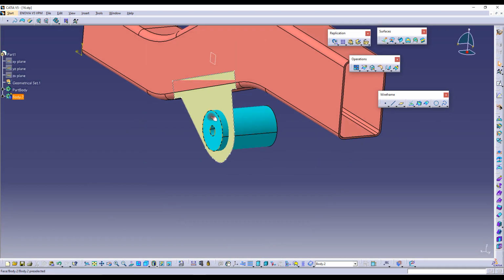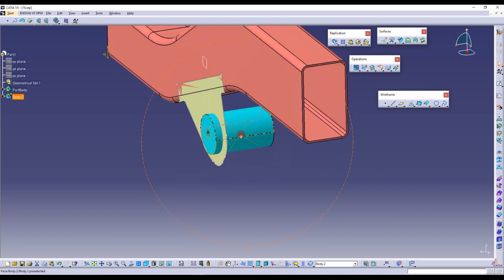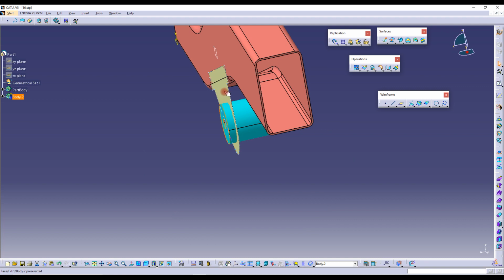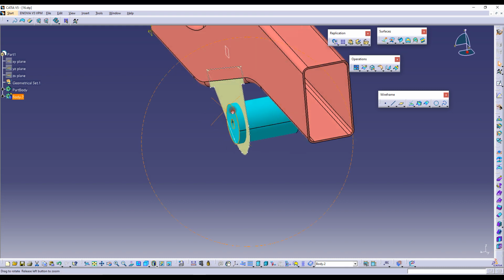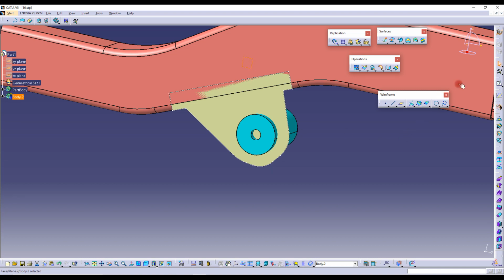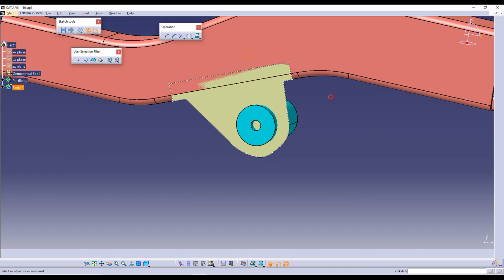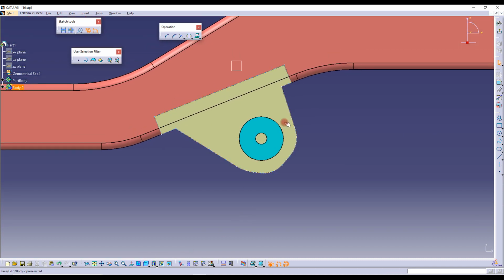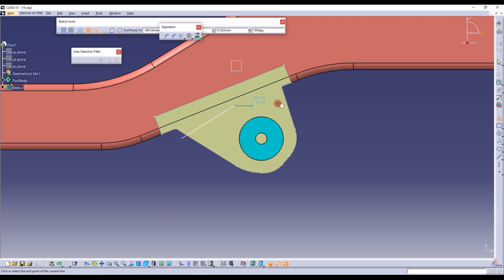As you can make out, the butting surface of the bush is protruding out of the surface. So that means that we need to make another offset surface from this base surface and then create a bulge, something like this, which goes something like this. So for that, we need to sketch over here on this plane again. So go to sketch, orient the sketch so that it's convenient to work on it. And let's create something like this, a line like this.